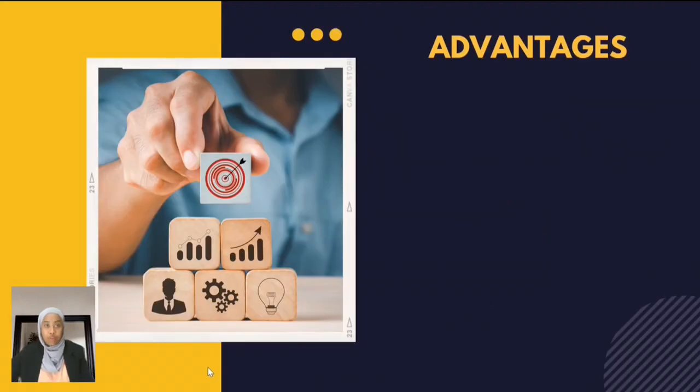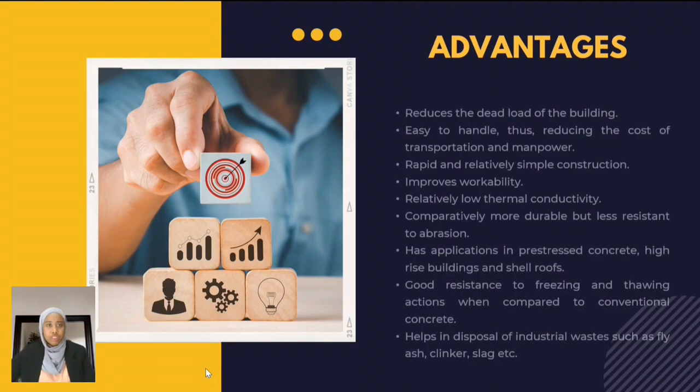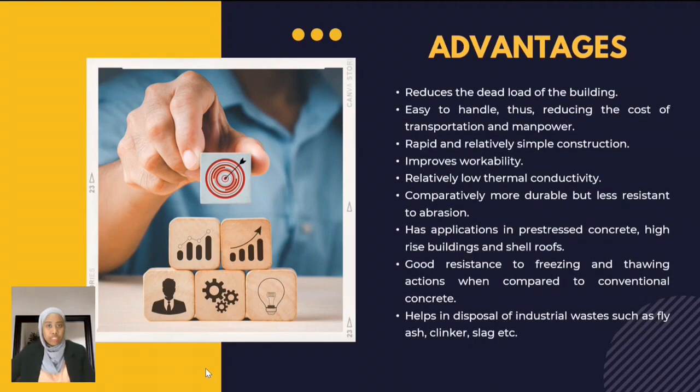For lightweight concrete advantages and disadvantages, first we see the advantages. The advantages of lightweight concrete are, first, it reduces the dead load of the building. Second, it is easy to handle, reducing the cost of transportation and manpower. Third, rapid and relatively simple construction. Next, improved workability, relatively low thermal conductivity, comparatively more durable but less resistant to abrasion, and it has application in pre-stressed concrete, high-rise buildings, and also shell roofs.